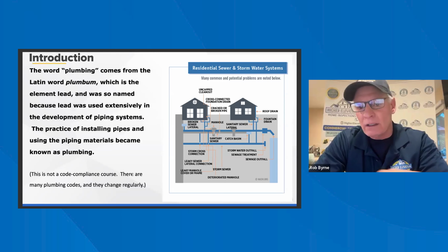We don't have one because our main water valve, shutoff valve, did not have a regulator. Some jurisdictions don't require it because if the water gets heated up, it can still push backwards. If there was a regulator or a backflow at the entrance to the house, we would need an expansion tank. As we're looking, if it would damage the house, we'd also need a catch pan. But since we have a concrete floor with a drain, we don't need one.